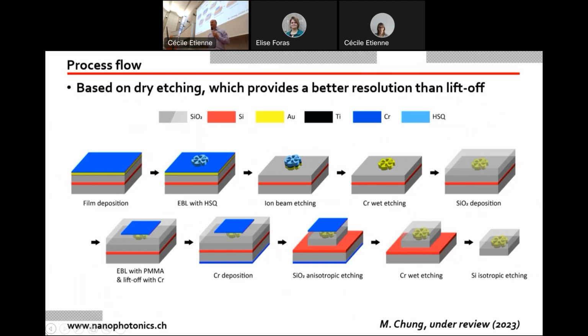On top of that, we had to fabricate the gold rotor. This is done by etching. So we have again our photoresist HSQ. We illuminate with the E-beam. We etch away the material. Here there is an additional step. Sometimes it's annoying that the mask that you've used to fabricate the structure remains on the top. This HSQ, this photoresist, is so solid that normally it will stay forever. So it's very hard to remove.